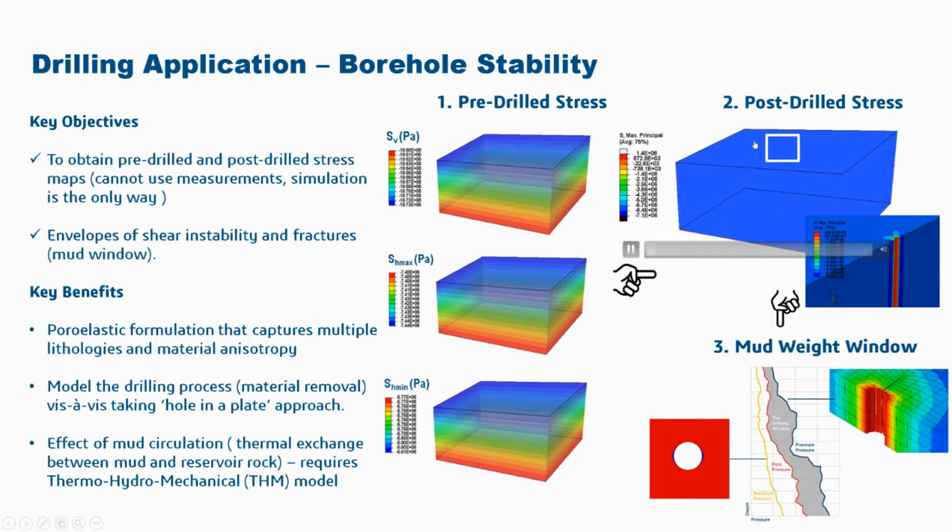And then we can also model the process of drilling as it happens. And we can calculate the state of stress around the borehole, and that information can be used to calculate what we call a mud weight window.